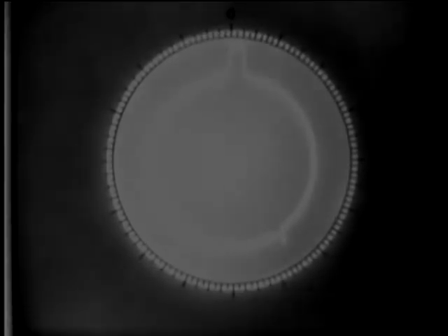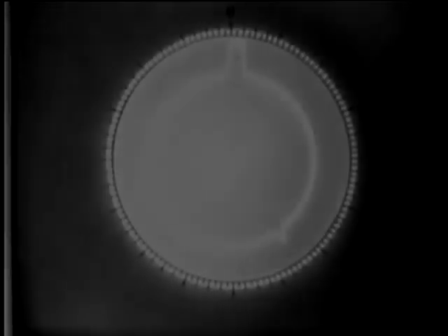Since our baseline is circular, to measure range, we simply put a circular range scale around the edge, with 0 at top center. By reading range clockwise to the pip, you can tell at a glance how far away the target is. Here's that same J-scope you saw earlier. It's the coarse range scope of the SCR 584 and measures ranges out to 32,000 yards.